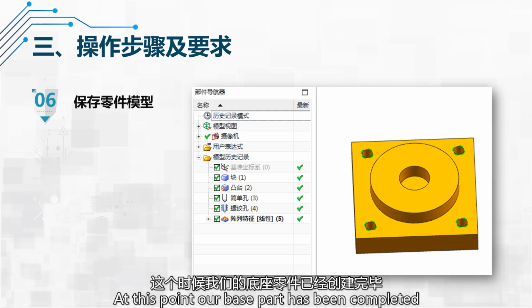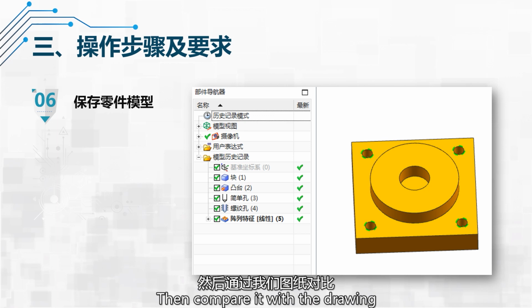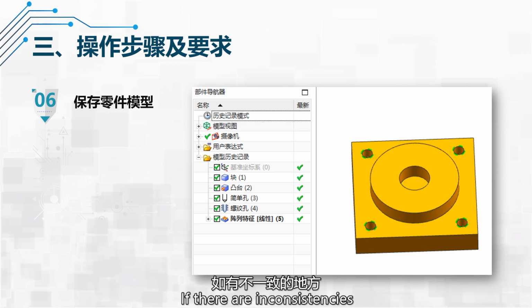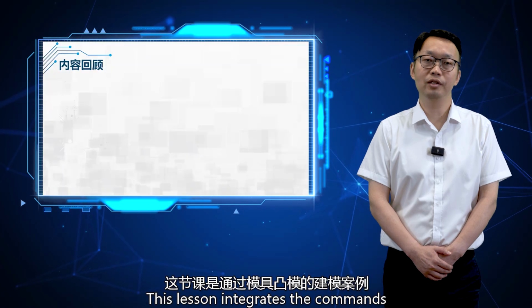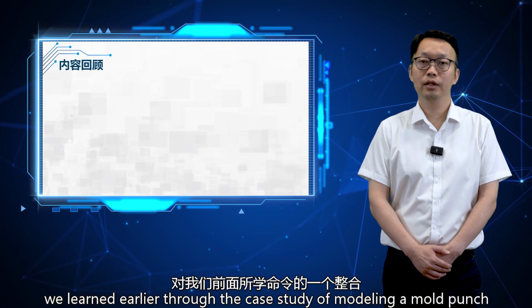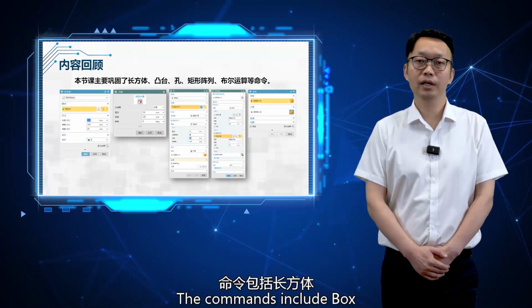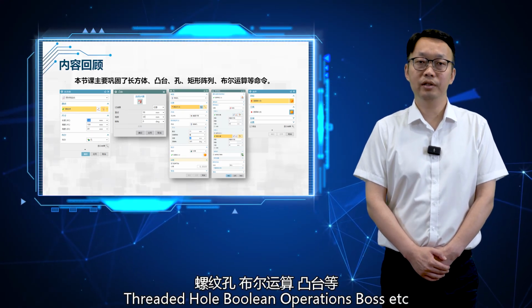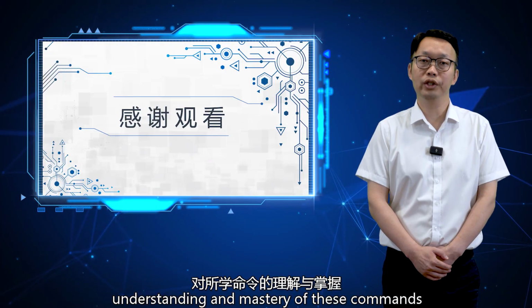At this point, our base part has been completed. Then, compare it with the drawing to check if there are any inconsistencies between the model and the drawing. If there are inconsistencies, check which step went wrong and make corrections. This lesson integrates the commands we learned earlier through the case study of modeling a mold punch. The commands include box, threaded hole, Boolean operations, boss, etc. The base modeling strengthens our understanding and mastery of these commands.